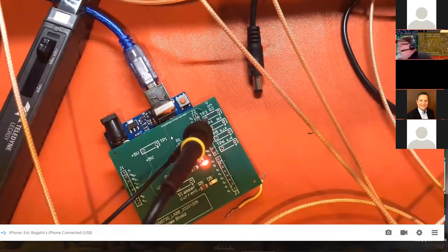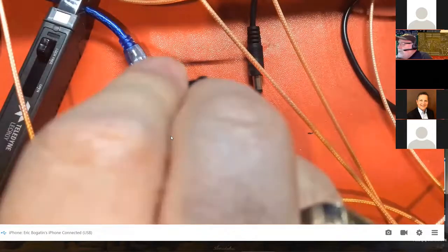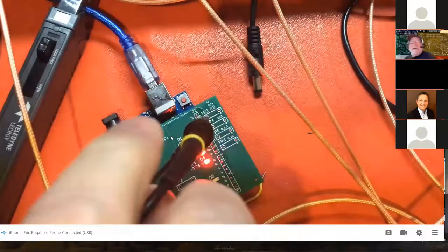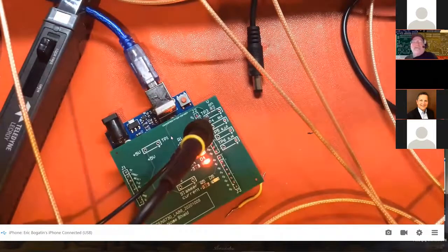And now we have a really low loop inductance tip that has the highest bandwidth we can get with the 10x probe, basically. Very little radiation, very little pickup. Still a little bit of residual, so it's not perfect, but it's the best we can do for this kind of convenience. And so that's really one of the important tips on getting the most out of your 10x probe.